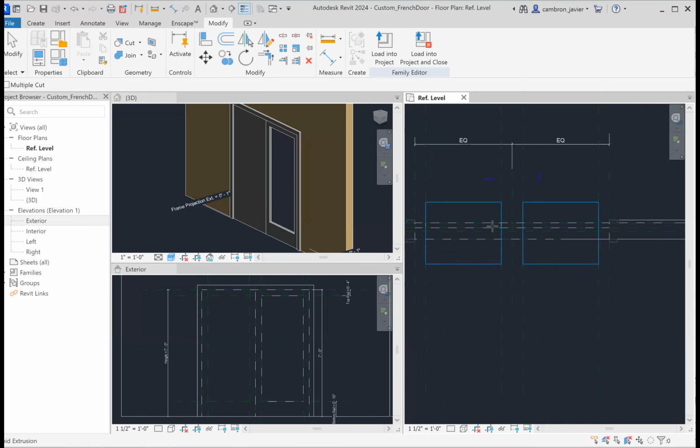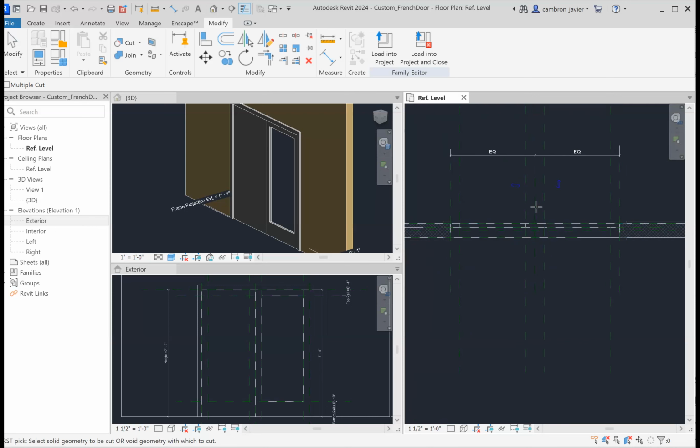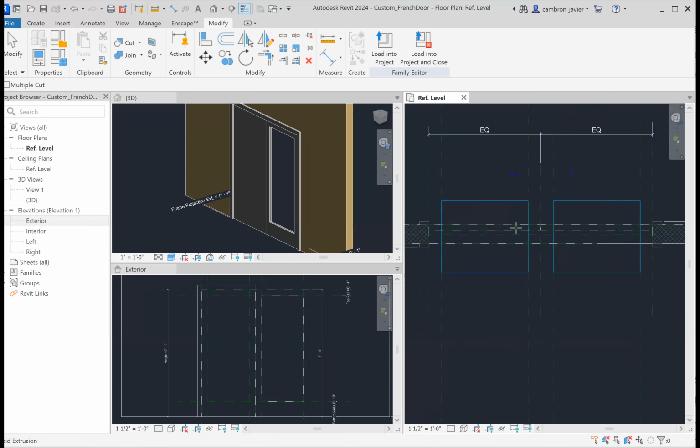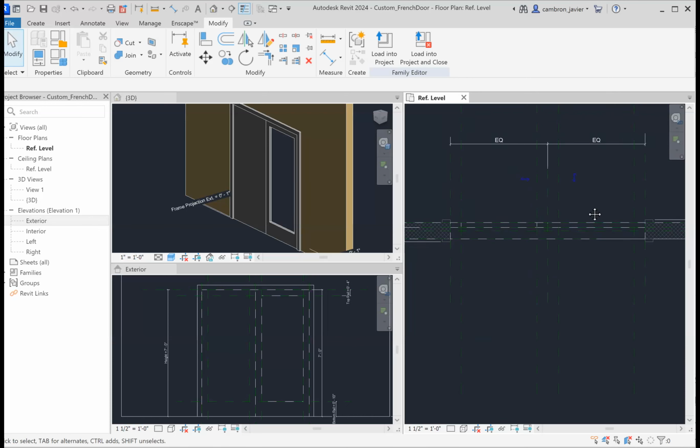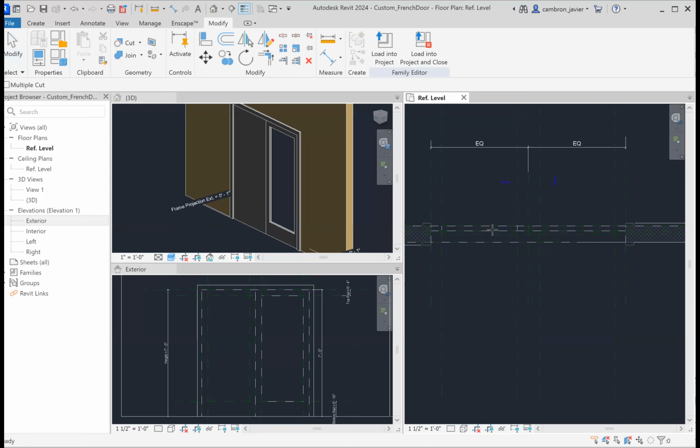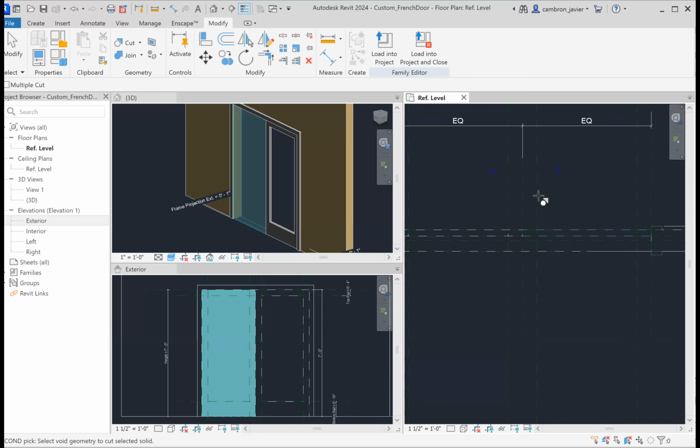We're going to do the same thing, but one of the things that you'll notice is that the void went away, right? Like it disappeared. It's still there. It's a little tricky, but if you move your cursor in between the doors, they pop up. They're just invisible. So let's actually just jump to the cut tool so we can cut the other door. So we're going to select the door and hope we can find it. Yep, this is the annoying part.